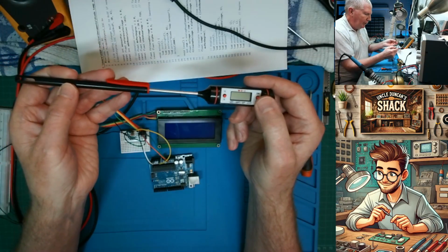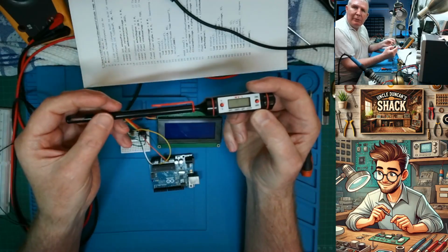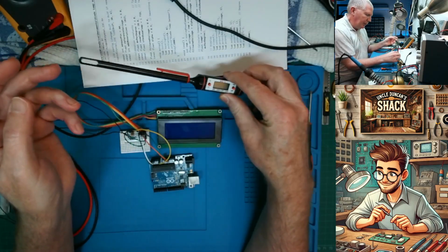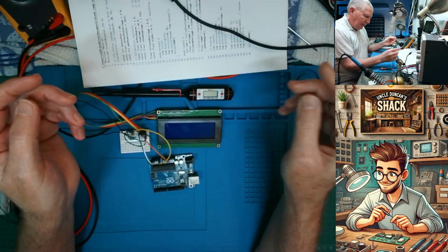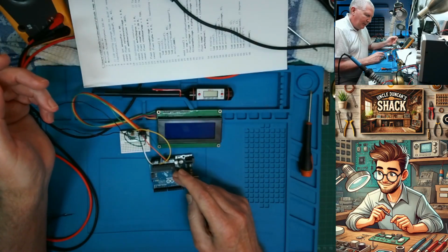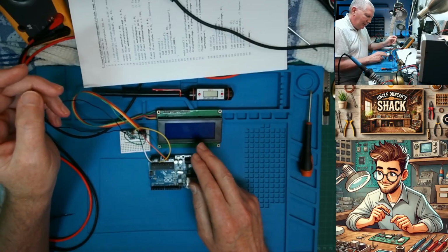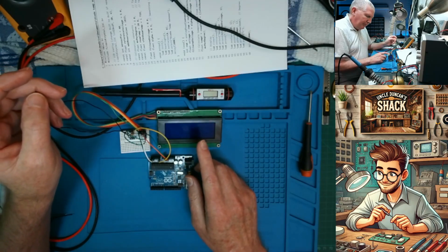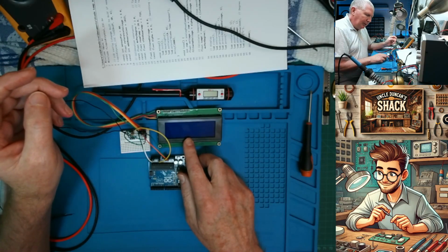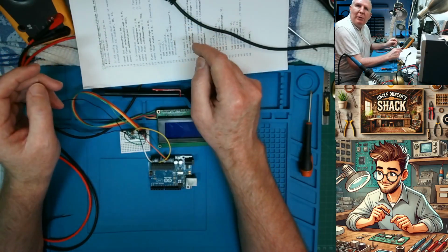So there's various types of temperature sensors. In this case it's solid state using a diode, and I've demonstrated how to hook it up to an Arduino. You just need a bias resistor, and if you want to see the temperature, just use a little LCD display. And there's your code over there, simple bit of code.